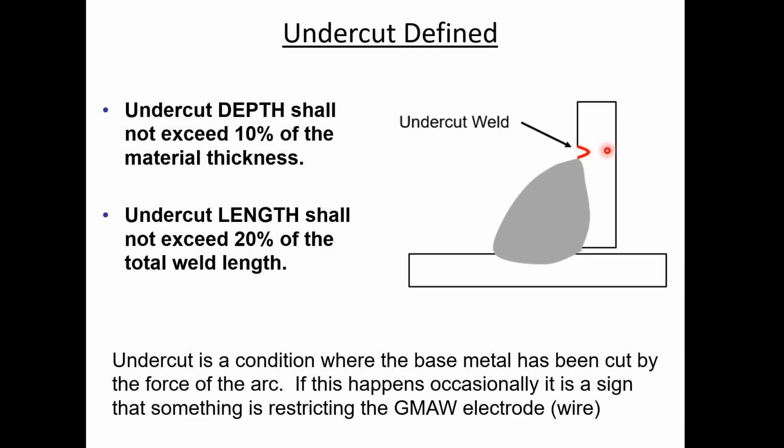Well, if this is a dynamically loaded material, they don't want this happening, because this is going to be a softer area, and it may as well have a big sign on it going right there that says crack here. And the dynamically loaded, especially in a structure, if it's part of the suspension or anything that's holding the suspension, right, it is going to be under all types of stresses. It's going to crack through.